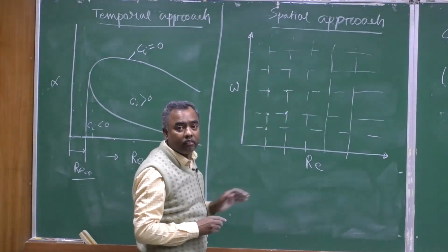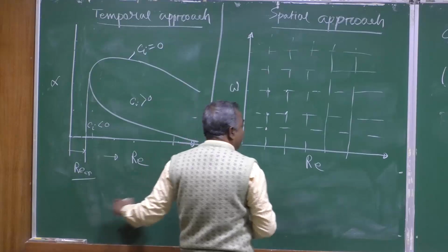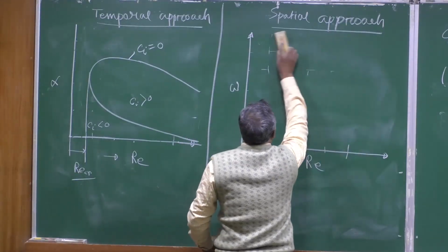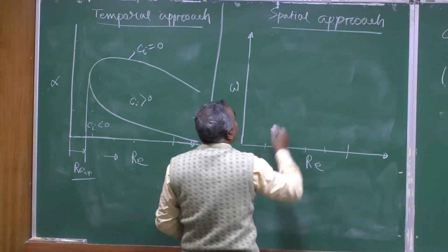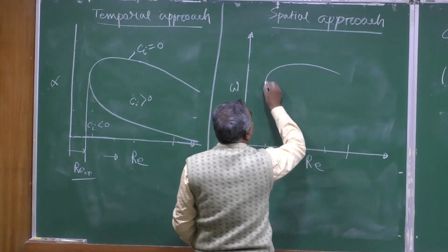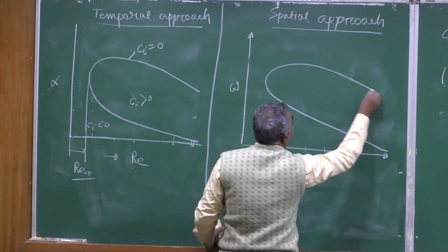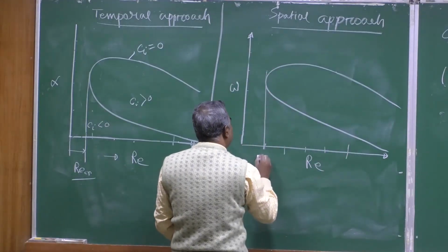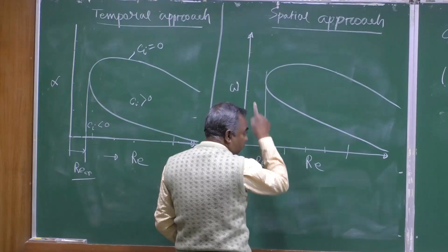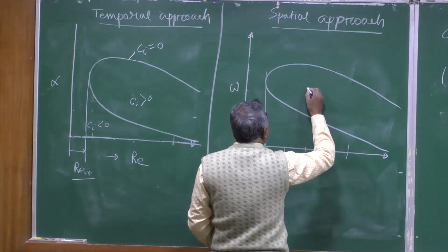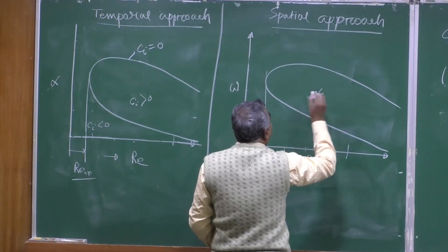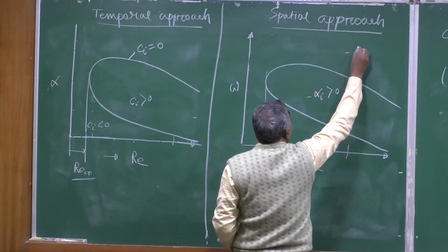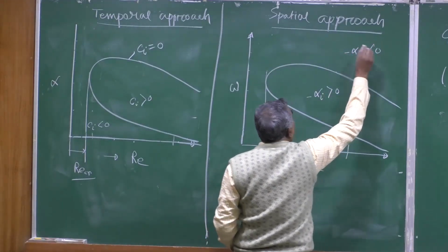Then you put a contour here. Okay. To interpret the result, you simply plot it in terms of the contour value. Let us say this is your alpha I contour. Okay. So, this is your minimum critical Reynolds number for this approach. Okay. And within this, your minus alpha I is greater than 0, and outside, your minus alpha I is less than 0.